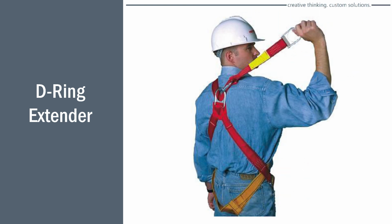They do make a D-ring extender, but if you use extenders and then you tie into a lanyard, you're increasing your fall distance. So be careful of this. Very careful. These were made because people didn't like to reach behind their back and connect the snap hook to the D-ring. Now you add a 6-foot lanyard on that, and you've added about 2 more feet to fall distance.